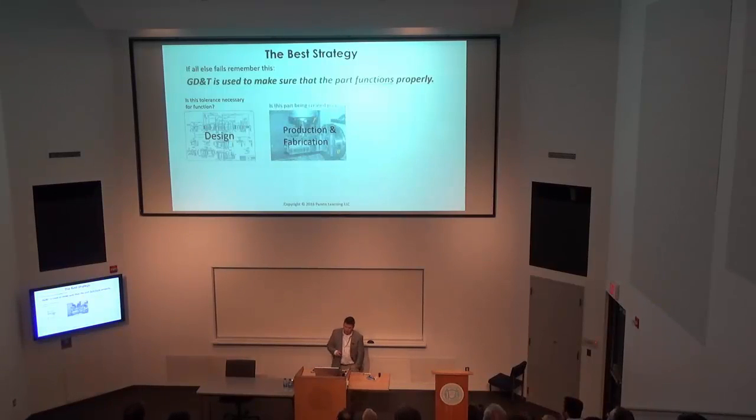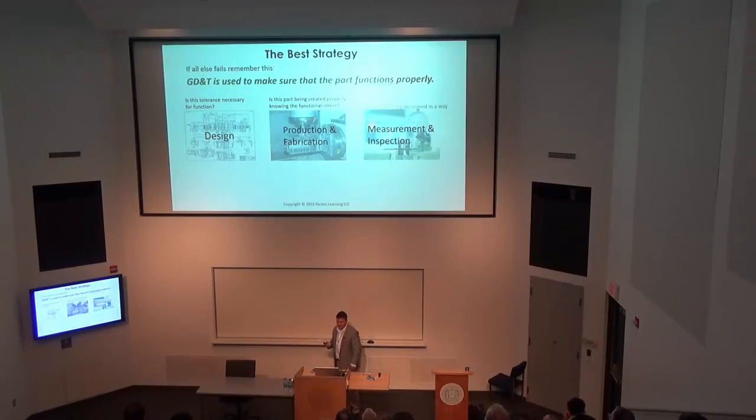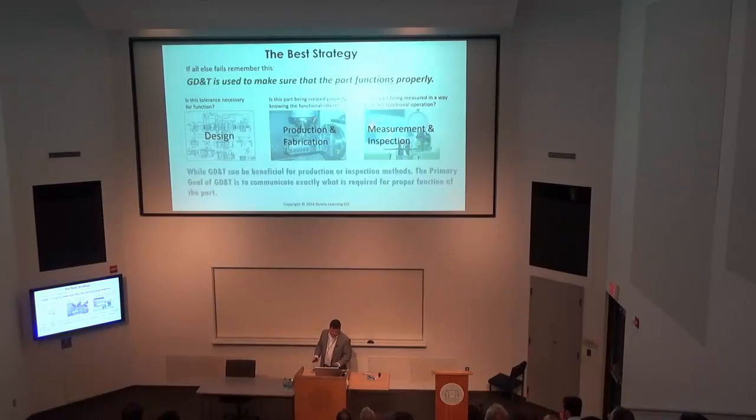From production, is this part being created properly, knowing the functional intent? Doesn't mean you have to create it exactly according to the datum reference frame, but you should keep in mind the functional intent. And finally, measurement and inspection. Is this part being measured in a way to mimic the functional operation? Am I doing this according to my proper datum reference frame? Because if you're not, then you're not measuring correctly.